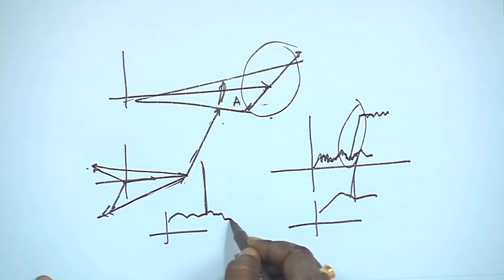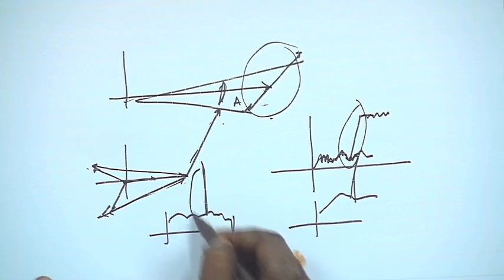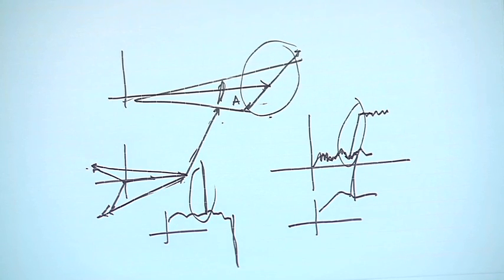So, what is the threshold effect? This is called click noise. Basically, after FM demodulation you will have that original message, which has nice noise cancellation, so overall noise cancellation will be good. The message signal will be smooth, but suddenly there will be an impulse and then again smooth, suddenly there will be an impulse. This will create a cracking noise in the receiver, one after another. Whoever has listened to FM radio might have heard those clicking sounds.